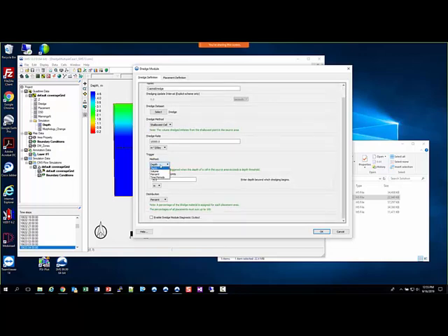For the triggers, like I said, you can base it on depth, or you can base it on a volume of material above the dredge depth. So that might be useful if you are monitoring an area, and whenever material is placed in this area, or through normal simulation it starts filling in, then you can tell it to automatically dredge those areas as needed.